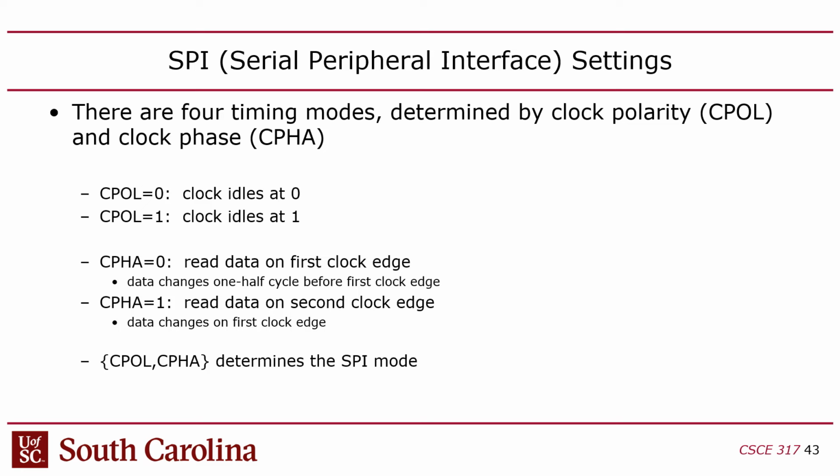Now, why couldn't they just standardize that? Unclear. I don't know. I think this all was maybe born out of some confusion. I think it's backward compatibility. There are a lot of devices on the market which use different modes, so you cannot standardize them because they are already there. Right, but I2C, it's standardized, everyone follows the standard. PCI, everything is standardized, everyone follows the standard. USB, standardized, everyone follows the standard. SPI, you've got to customize it because not everyone speaks exactly the same dialect here, right? So you can think of this as a dialect of SPI, right?